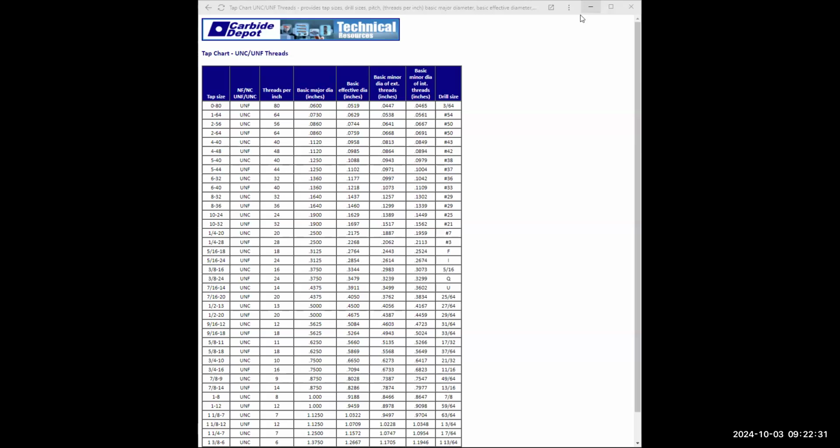Now, see how I kind of got more space there? I want to move that. I typed in M because I want to move that. Click on what I want to move. Click, enter, click, and just drag it up a little bit. Right there. Up. I didn't want it to do that. The reason it did that is I've got the F8 on. Turn F8 off. Now I can move it. Select, type in M, enter, select your text, enter, click somewhere near your text, and just move it.